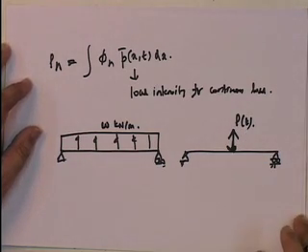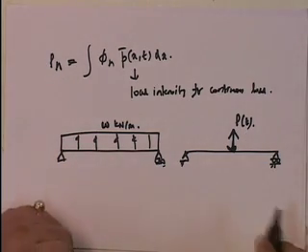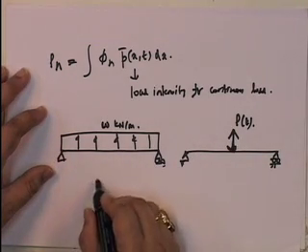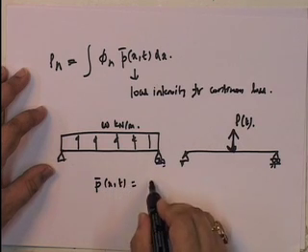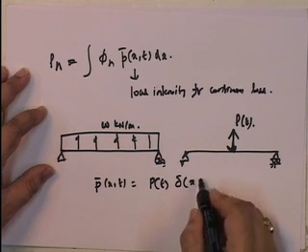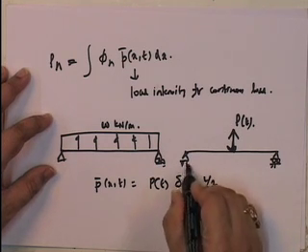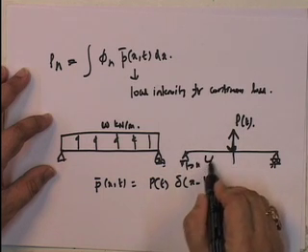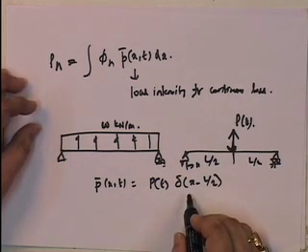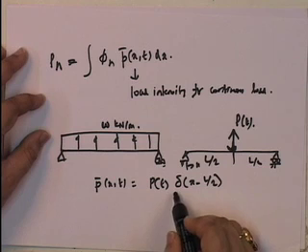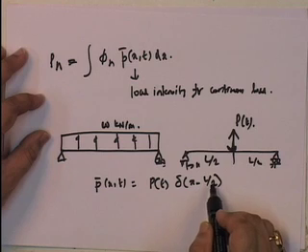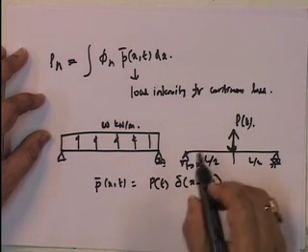How would you solve this problem? Well, there are two ways of solving this problem. Writing this as a continuous load, the P bar x t essentially becomes P of t Dirac delta of x minus L over 2. This is like, let us say, L over 2. A Dirac function is nothing but a value that is 0 for every value where x is not equal to L by 2, and it is an infinite value at that point.